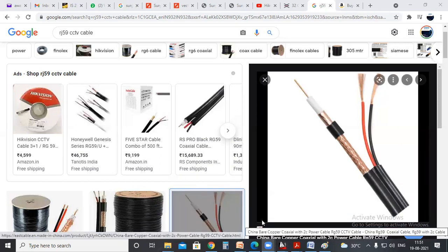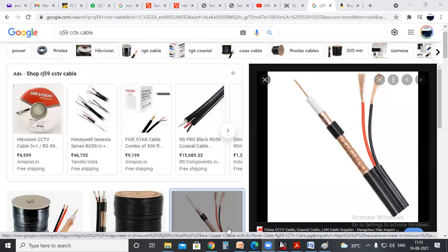Okay, so another question was maximum length. It is better to get good visuals up to 100 meter. If the length is more than 100 meter, the signal loss will be there. You can maintain by providing a network switch or something like that. You can overcome that. But for the normal case, if the length is more than 100 meter, it would affect the signal strength.